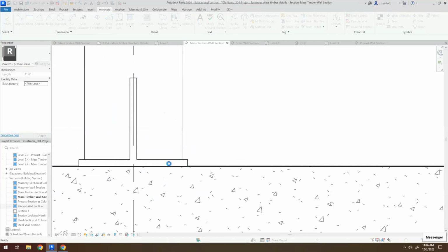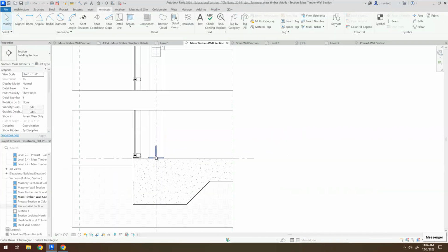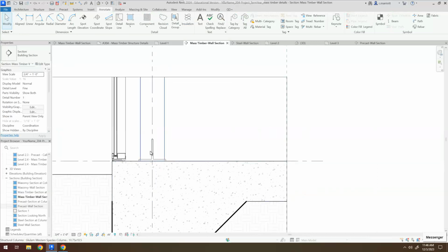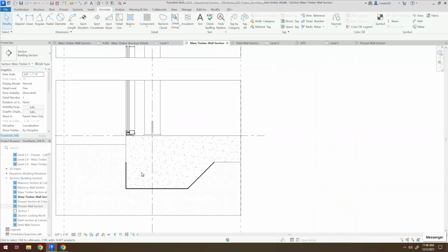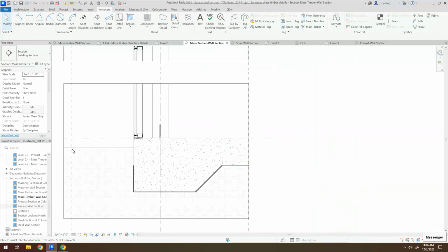Okay, so there may be some fasteners, and we just kind of want to suggest that there is some consideration of how this column is going to sit on the slab. It's a good idea that the wood not directly touch the slab. Okay, for the very final part of what we see here, we want to have a pitch that allows for drainage away from the building. We want our rebar in here. We want the crushed gravel, a lot of the same details that you've been drawing on the other details, and you should be able to copy and paste some of that information to this one.